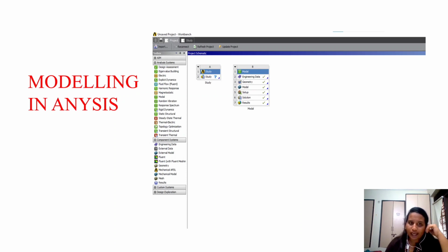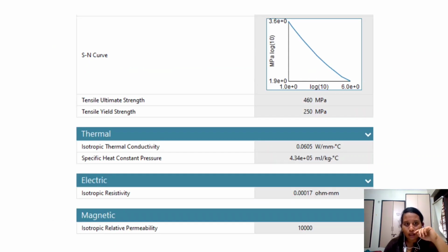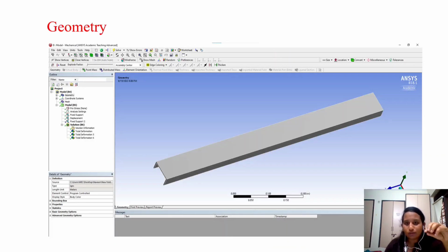After the experimental work was done and I got the MATLAB results, I did the same thing in the ANSYS software. This is the home page of the ANSYS software. There are different types of contents, like materials and everything. These are the properties of the steel I have considered, like Young's modulus, Poisson's ratio and tensile strength; whatever you want, you can give to your structure. After that we have to give the geometry, like length of the beam, height, width, and the properties of your geometry.